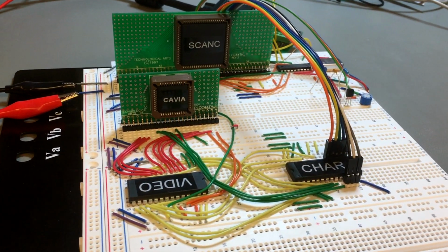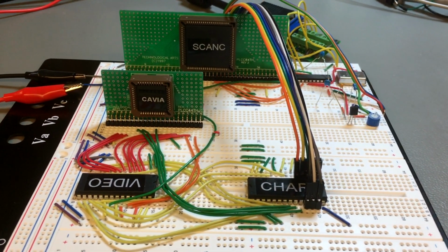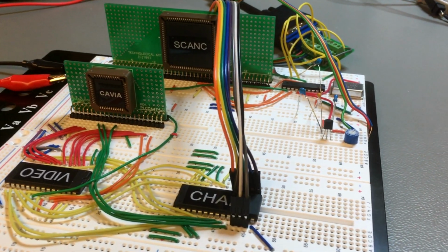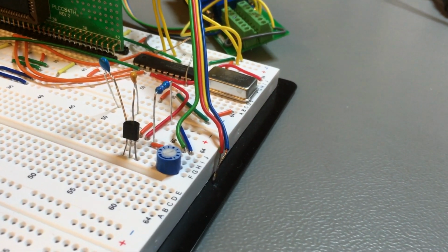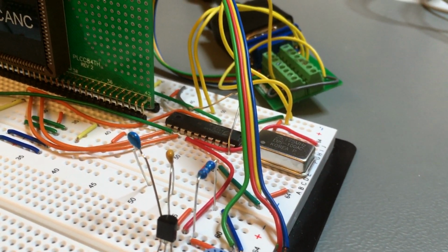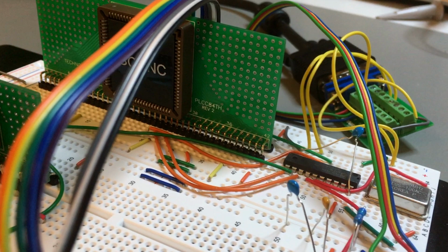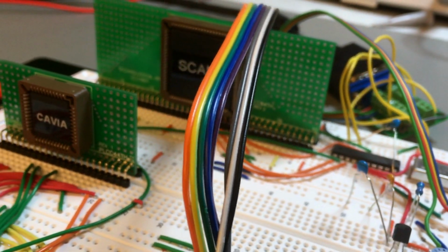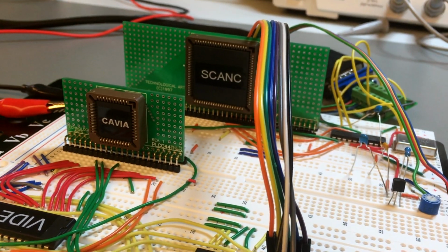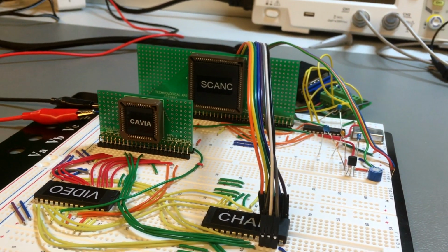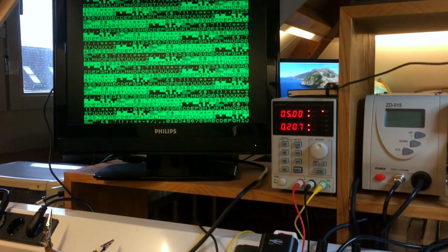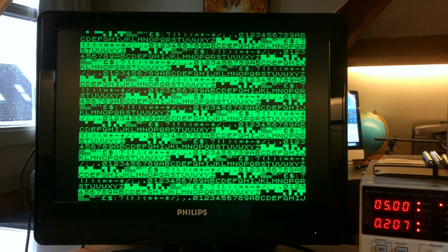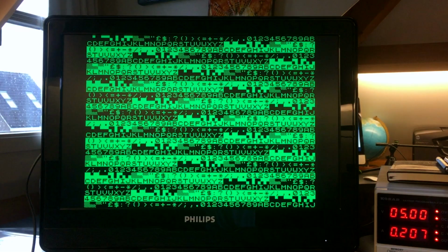Kavya now has the proper breadboard adapter, so it's now sitting in a self-contained breadboard with all the components we need, including a little trim potentiometer that you saw down there. There's a little buffer as well. I'll explain all this in a second, but it's a self-contained breadboard. All the pieces are in there. It only receives power from the outside and produces a video signal that also happens to be quite perfect. I changed the television settings for it to display the original 3x4 format instead of a stretched out 16:9.